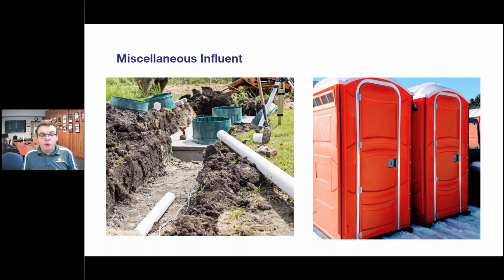For porta potty waste, on the other hand, it's going to have a lot of biocides in it, and if you don't manage those biocides or meter how fast you're putting them into your lagoon system, if you take in a large amount of this biocide, you're going to completely wipe out the ecosystem that you formed for your lagoon system.